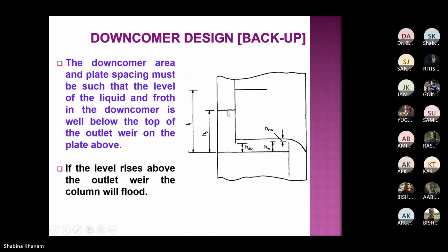To avoid flooding, the condition is that whatever level of liquid is available in this downcomer should be lesser than the plate spacing.